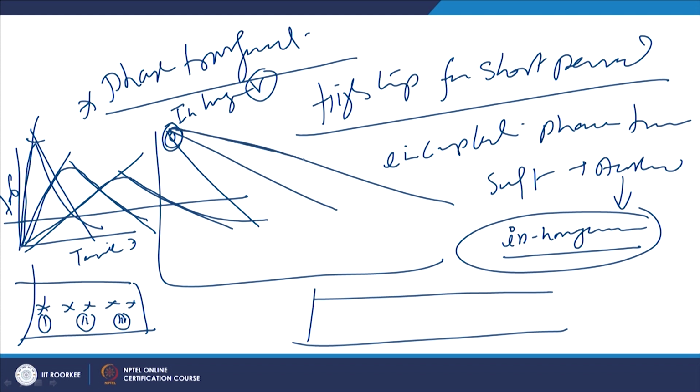The point which is at the largest distance away from the fusion boundary will be experiencing a low cooling rate as compared to those which are closer to the fusion boundary, and accordingly the austenite will be transforming into different phases.